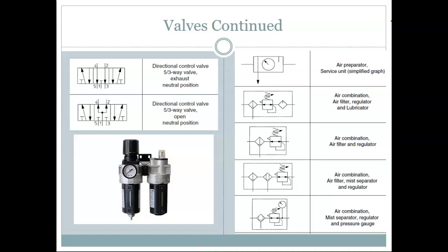Rust will happen first. Air doesn't mind being compressed. It's not hydraulics. But what you're going to mainly have an issue with is rust. And that is something that happens far too frequently with compressors. If you really look at a lot of the really old compressor tanks, they're pretty rusty.